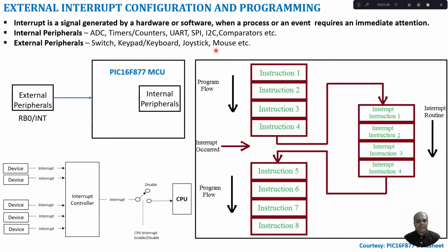Whenever I press a switch on a keyboard, that can be used as an interrupt signal to the CPU. Once a keyboard key press is obtained as an interrupt, the CPU will try to execute a program related to that keyboard. Thereby it identifies whether it is a valid key press and tries to recognize what key has been pressed, whether it is a key A, B or numbers. Depending upon the application, the recognized key can be sent to a Word or Notepad, etc.